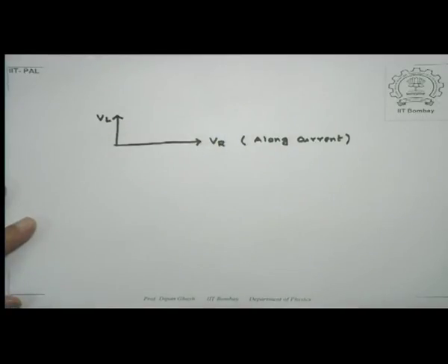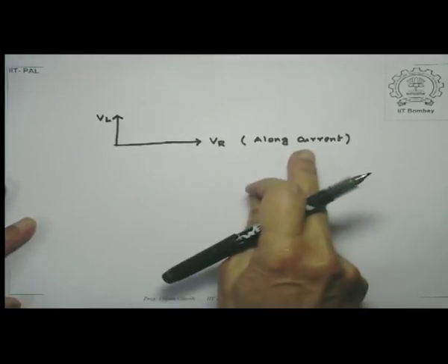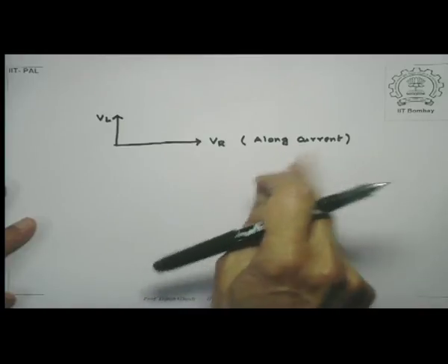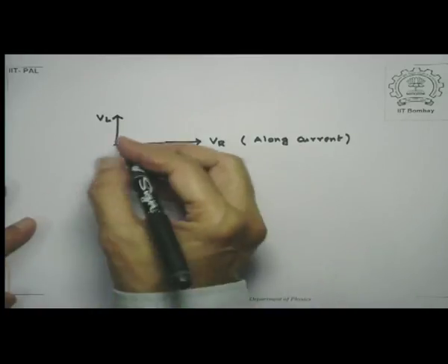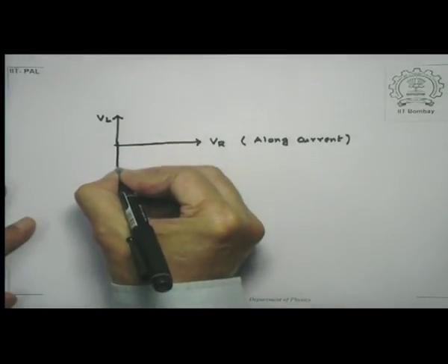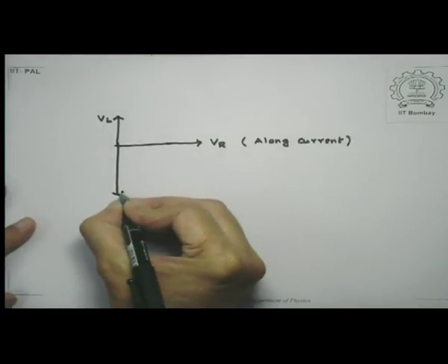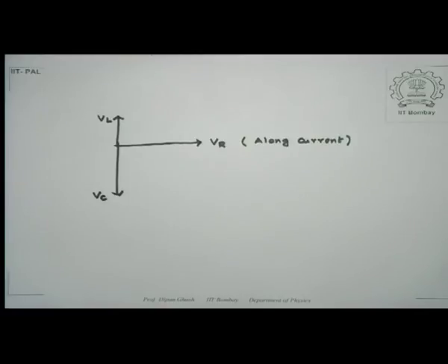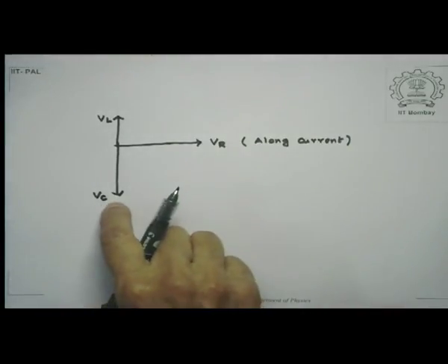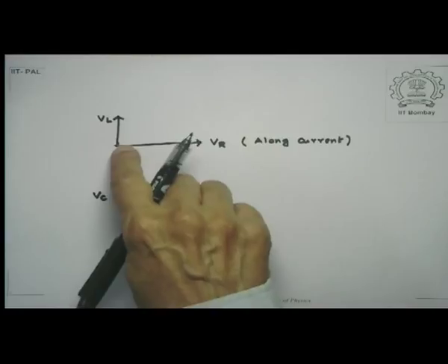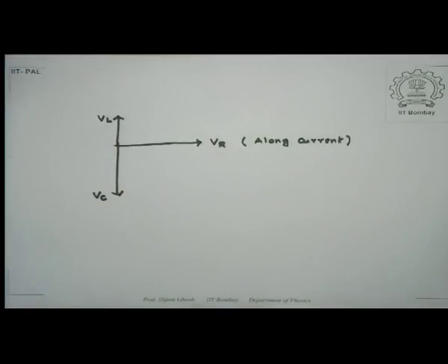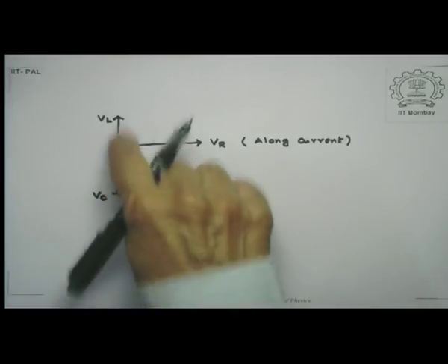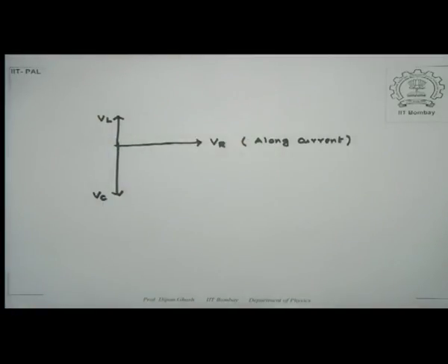And for a capacitor, since capacitive voltage would lag the current because capacitive current leads the voltage, I would put the capacitive voltage along this direction, and let me, without loss of any generality, take the capacitive voltage to be larger than the inductive voltage, and of course if the reverse is true, then my drawing would change accordingly.